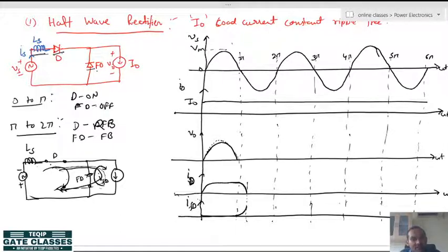So, you see in this duration, when both diodes are turned on, both are short circuited, it means the output voltage during this period will be 0. Alright, output voltage will be 0 here. From here onwards the diode current will be 0 and the freewheeling diode current will rise up. This overlapping you see here is known as the overlapping angle mu.